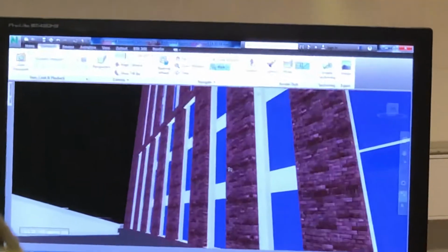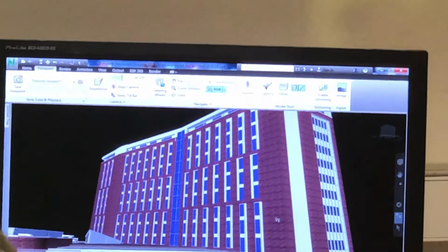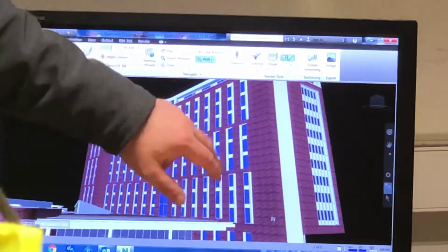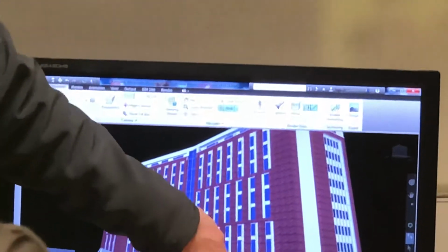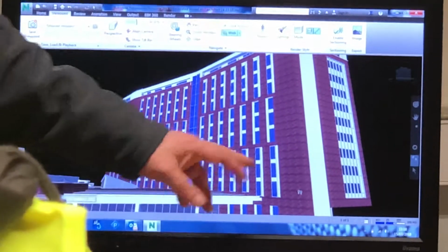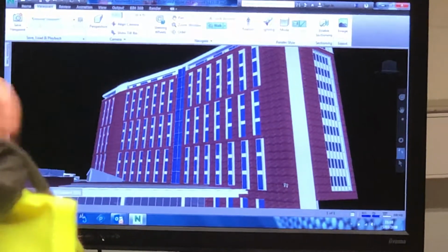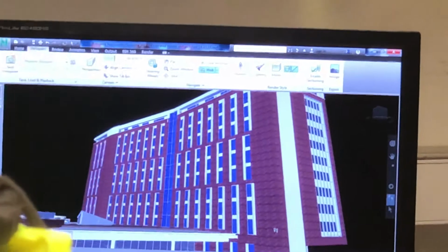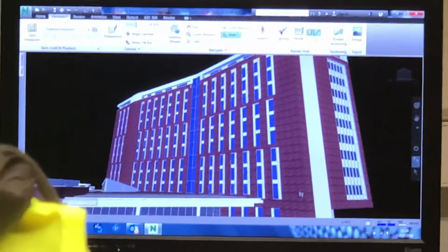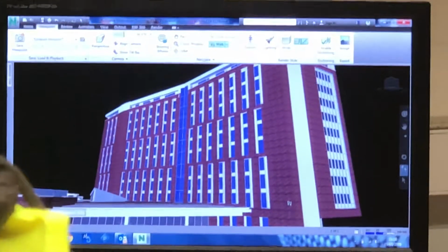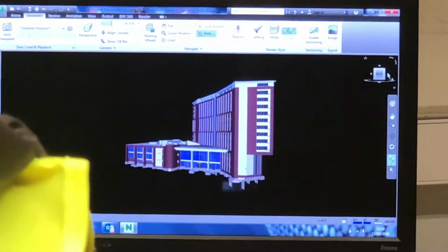Right, here, also the windows, and you can see from our elevations, we're 13 stories, it's mostly brickwork. There's a 3-story fenestration pattern that continues up, and that's a piece of cladding with glazing units in it. At every 3rd floor there's a brickwork support angle, which then allows us to load the brickwork going up. I say it's mostly brickwork. There's not a lot of cladding on this project, which is a bit different to most of the other high-rise jobs around here, because most of them are clad because it's lightweight and it's quick. Our architects have decided to go for a more traditional approach to it.